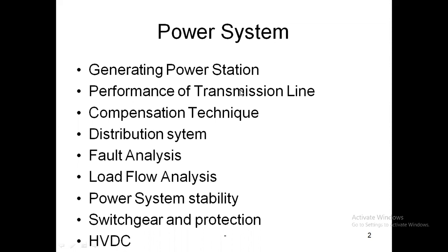After that, when we transmit the power from one place to another place, from where we can utilize that power, we will have the distribution system. In the distribution system, after getting the power from the transmission system, we will be stepping down that power, because the transmission line has a large voltage level. Because if we transmit the power at a low voltage level, then there will be low power capability of the line, and the losses will also be there on the line.